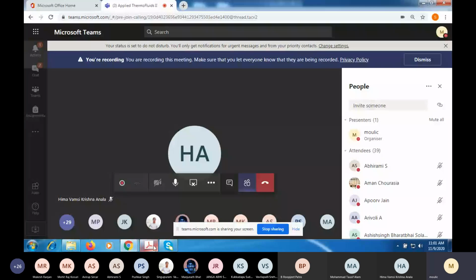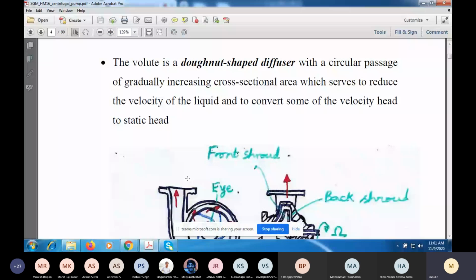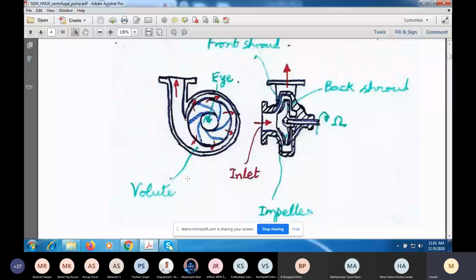All right, so last time we were looking at the performance of a centrifugal pump, and to quickly refresh your memories, these are two views of a volute type pump. The fluid will enter axially through the eye in a direction perpendicular to the screen. So it's a three-dimensional flow. Then it will turn, and the axial component will turn into a radial component and a tangential component.